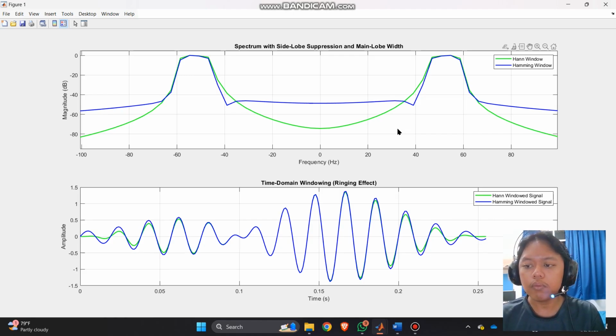Meanwhile, in contrast, the Hamming window is particularly used for applications that demand high frequency resolution, such as to identify harmonics or closely spaced tones in audio analysis. It is also applied in communication systems to resolve closely spaced frequency components in modulated signals, and in radar or sonar systems by detecting narrow signals in noisy environments. Its ability to provide fine spectral detail makes it suitable for high resolution spectral